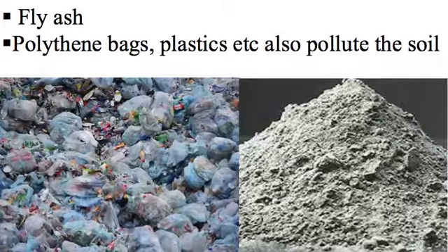So, fly ash or flue ash, commonly known as pulverized flue ash, is a coal combustion product that is composed of the particulate, that means fine particles of the burned fuel, that are driven out of the coal-fired boilers together with the flue gases. Ash that falls to the bottom of the boiler combustion chamber, commonly called a firebox, is called bottom ash.